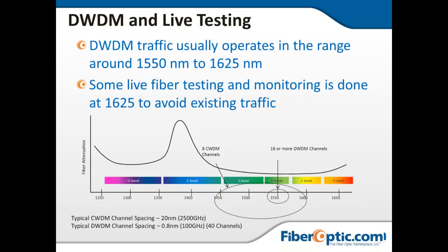And here's an example of what we're talking about with the DWDM systems. The graph here, which is important, shows that between 1350 and about 1400 there's this huge black spike in the fiber attenuation curve. That's why for a long time, in the O band, which is the lower band on the optical spectrum, 1310 was the point with the lowest fiber attenuation on that side of the water peak.